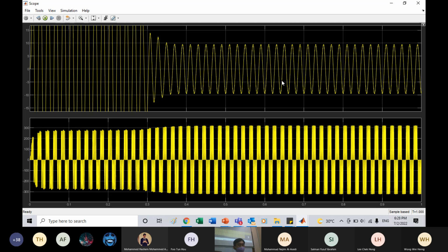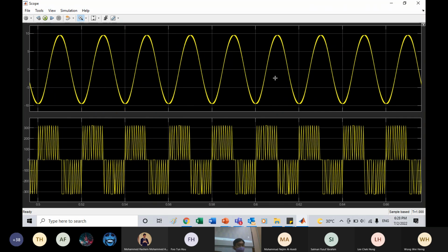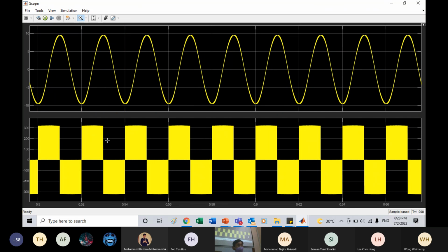So when we use SPWM, we can produce this beautiful sine wave as output, which will have a THD of most probably less than 10 or 5, I'm not sure, I never measured. Because it is not connected to the grid, still okay. But this is one of the fundamentals to apply to a motor, because the motor is inductive, so it acts as a filter that will produce a sine wave.